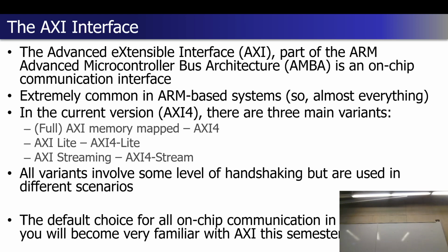You'll hear different terminology for that as well. If you just see the term AXI 4 describing the bus interface, that's referring to the full AXI 4. The other term you'll see is the memory-mapped AXI interface, and we'll talk about why it's called that. There's also the lighter version, AXI 4 Lite. That's just a subset of the full standard, and it's useful for certain things where you don't need the full standard. And then separately, there's the AXI Stream standard, which shares the same name, but doesn't actually do something similar. It's more of a FIFO-type interface for AXI systems. They all are going to involve some level of handshaking, but they're going to be used in different scenarios.